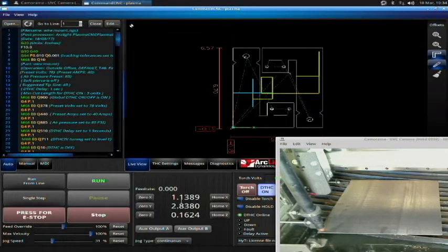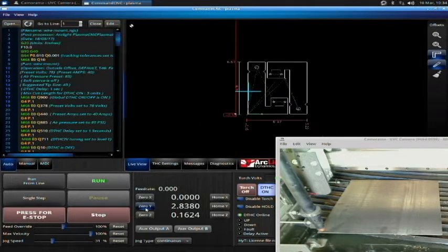It's a very easy way to lose your part. Okay, so with the position where I want to make the cut, I'm going to set the part 0 by going 0x, 0y, 0z. So as you can see, it has moved the part up and to the right. My machine 0 is still set down here, and now I have a part 0 where I need it.